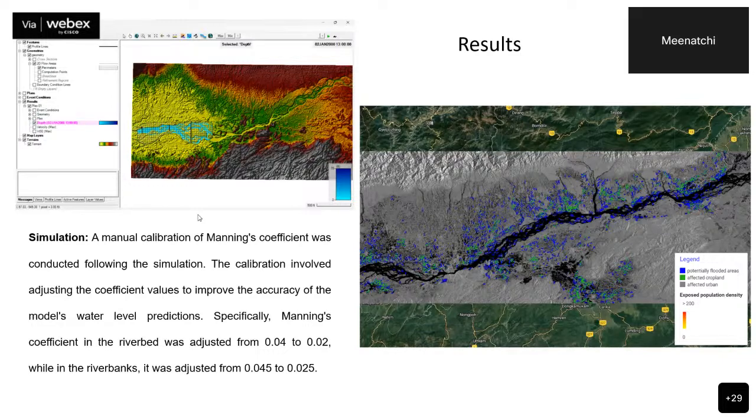Here the diffusive wave equation has been used, and it requires fewer computational resources compared to more complex equations. So the efficiency allows for faster model computations, enabling the analysis of larger and more extensive river systems. It is commonly used and appropriate for steady and unsteady flows.